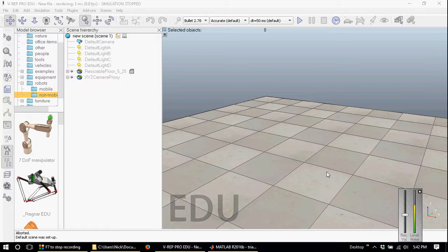Let's set up the VREP environment, and we'll start with a blank scene. The only thing that we really need is a command to be executed that's called simExtRemoteApiStart and then the socket number. For the purposes of this tutorial though, we'll do a little bit more. We'll add a robot agent and an obstacle.